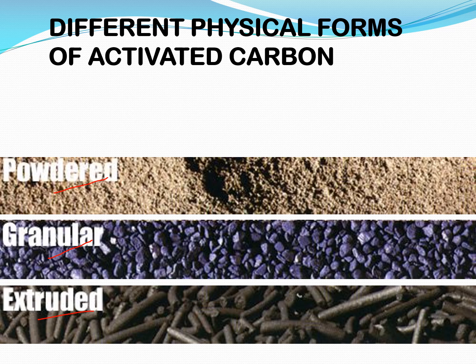The basic thing is that as you reduce the size, the surface area increases and you have more opportunity for the adsorbate to get adsorbed on the surface of the adsorbents. So by reducing the size, you can increase the surface area. But on the other hand, if you have smaller size particles, the pressure drop will increase. That's not favorable or required. So we choose an optimum size so that you can have maximum surface area, and the pressure drop is also retained at the required level.